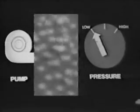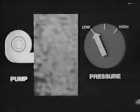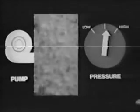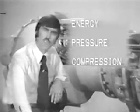Another property of air which is important to turbine operation is compressibility. If we attach a pump to our container, we can add more air molecules to those already there. Should we continue to pump air into the container, we would see the pressure rise. It's easy to see why. With more molecules, the number striking the wall at any single moment increases. Since each molecule exerts force on the wall when it collides, it makes sense that pressure would increase when more molecules are pumped into our container. So, energy has been converted into pressure through compression.